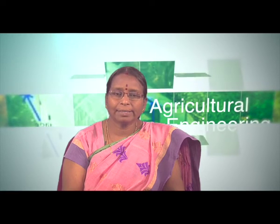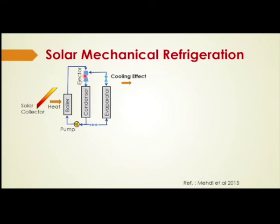In the previous one, they are using a compressor for the solar mechanical refrigeration system. Here another one is ejector based. In the solar mechanical refrigeration system, two types are there. One is the Rankine cycle based solar refrigeration system and another one is the ejector based solar mechanical refrigeration system. This diagram uses one ejector, so it uses an ejector in place of a compressor.